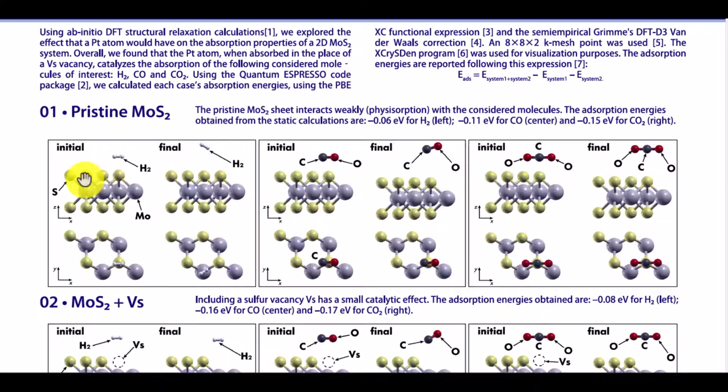So it's sufficiently big so that, considering that we are using periodic boundary conditions in the software, there is a sufficiently long distance between repetitions, for example, of this molecule and the molecule in the repeated cell. So we can be sure that we are focusing on the interaction between the molecule and this substrate.